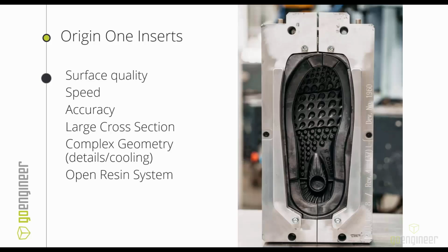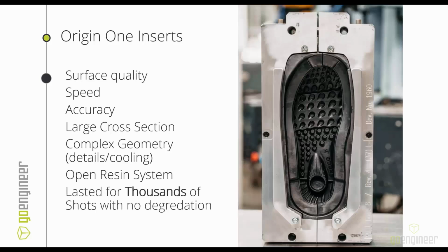Get to a point where you're happy and you want to move on, and not moving on just because you have to. And depending on the geometry of the part and the temperatures you're shooting into it, you can get thousands of shots. So specifically for Eco, they were able to get thousands of shots into these 3D printed molds without degradation on the mold. And specifically because what they're shooting in, for shoe rubbers, are not super high temperature. They're not high temperature glass filled nylons that are going to wear down the mold really quickly. So it works really well for that.